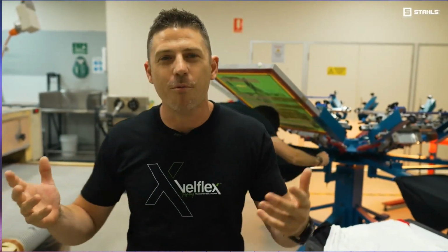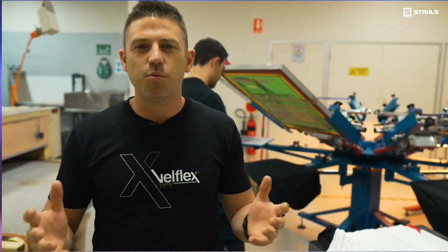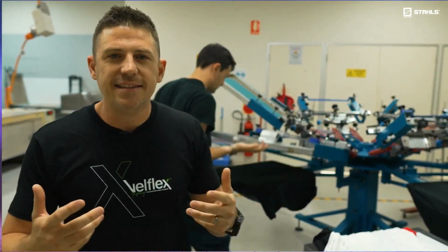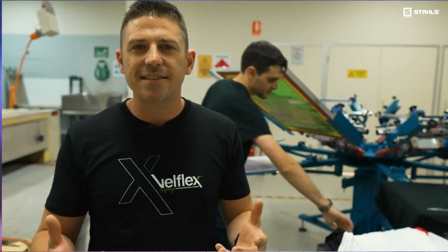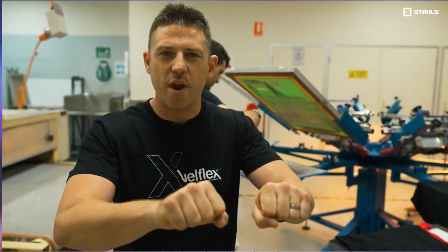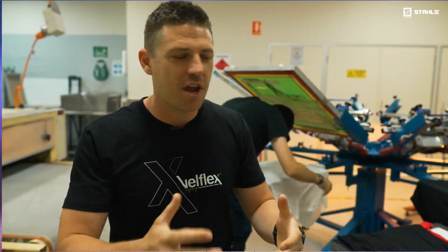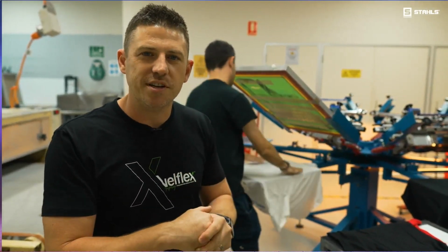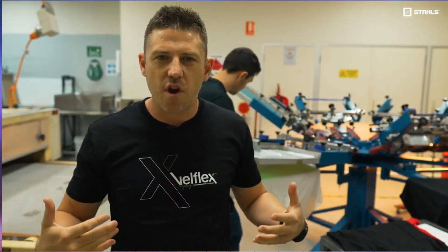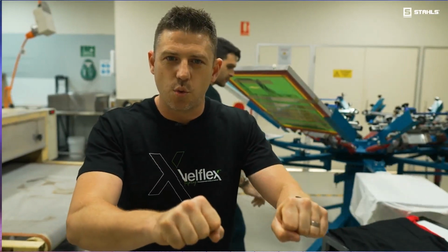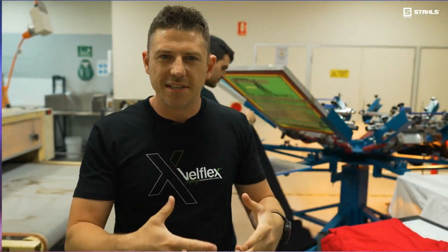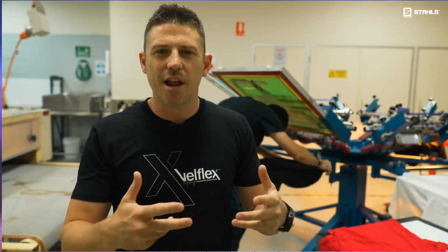Now, first off, screen printing. We're in the screen print room right here. What is screen printing? Now, it's one of those real traditional garment t-shirt printing processes. Been done for decades, guys. And if we look behind, it's done using an ink, typically a plastisol ink, and it's printing and squeezing that ink through a mesh down onto the garment that you're printing, right? So it's using a big screen that's a mesh, and it's had a stencil made on it. I'm going to show you how that's actually done also as well. And guys, you're literally squeezing the ink through onto the t-shirt or onto the garment. You might do a couple of passes.